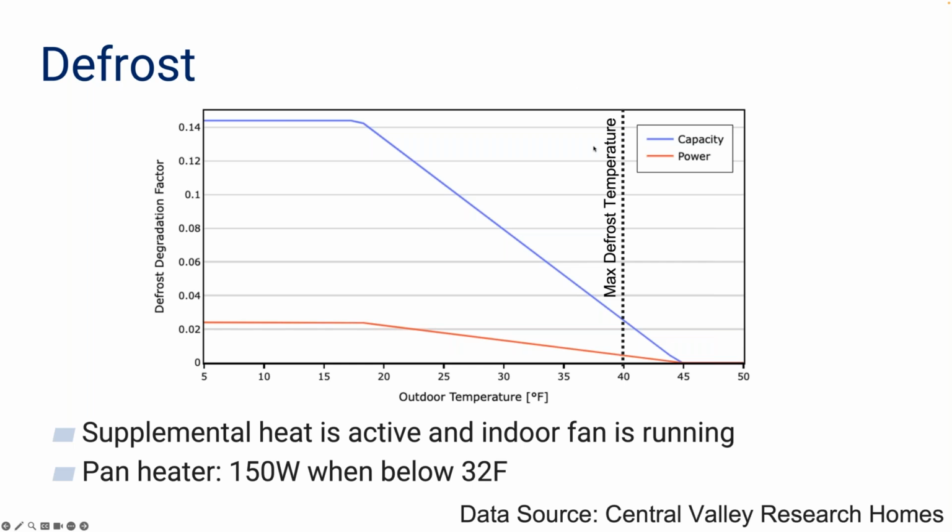defrost should actually only kick in at 40 degrees. This is something that might be unit specific or installation specific, but for the sake of this, we're going to impose this assumption. So really anything above 40 degrees, there would be no defrost. We also assume that the supplemental heater is active and the indoor fan is running when you're in defrost, and that there's a pan heater outside when the temperature is below 32 degrees.